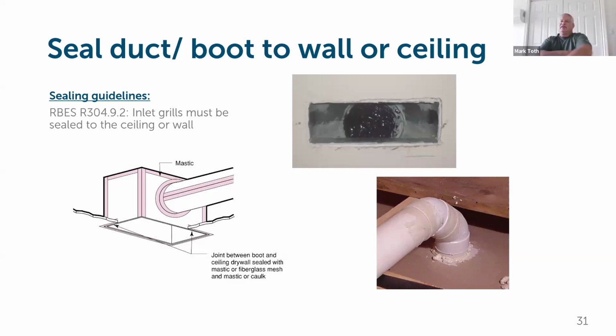We see it in regular HVAC systems too, where if the ductwork isn't sealed properly, and you're pushing a couple hundred CFM through some of these systems, a really small space that's not sealed, like on a duct that doesn't fit properly, you might have a 1/4 inch by 3 inch long gap. You can push, I don't know, 50 CFM through that. It's amazing how much air will leak through a hole in the ductwork that's not sealed. So very, very important.